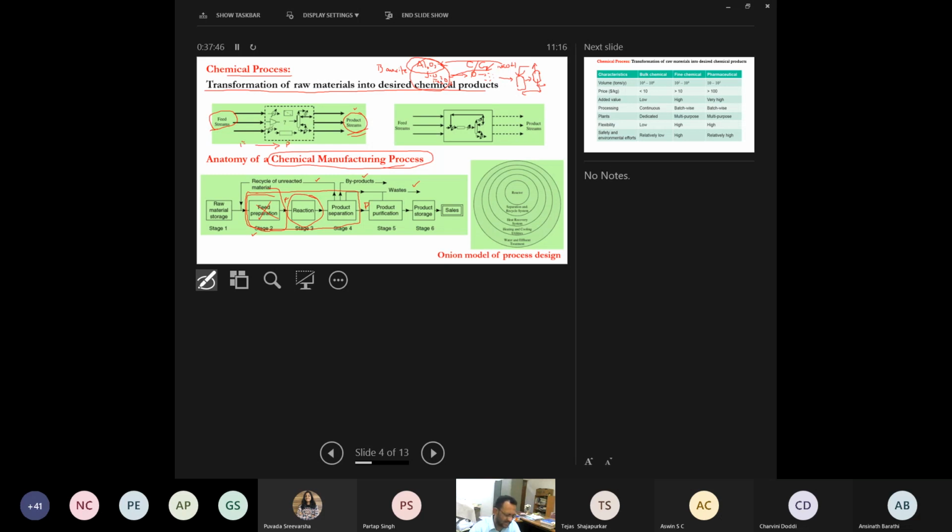So the sodium aluminate is again dissociated into Al2O3 and NaOH. This Al2O3 is separated, then this diluted NaOH is again sent to the evaporators, where it is concentrated again. That's why it's called a cyclic process. So you have bauxite plus NaOH, you will get sodium aluminate. Once you separate Al2O3, this NaOH is concentrated and sent back to the process. So this is a cyclic process.